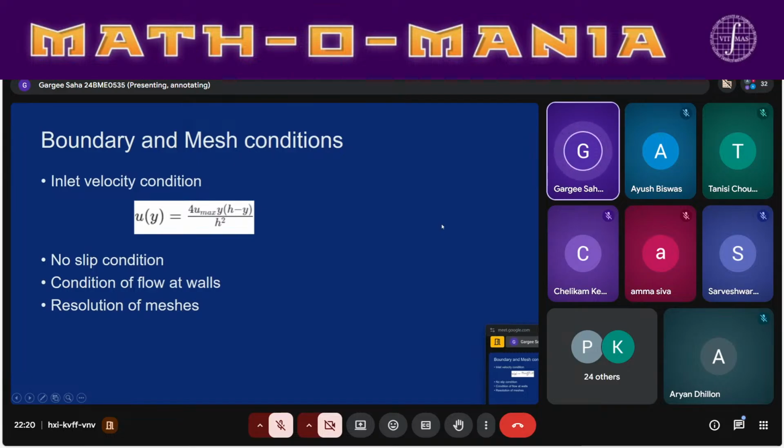If we used a flat velocity, the simulation would spend the first part of the time to basically channel this length artificially into the condition, and it will waste a lot of computational power and thus cause stability issues near the entrance. Let us now discuss the walls of the cylinder.